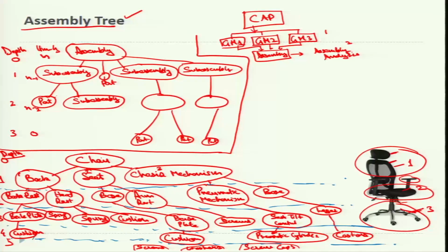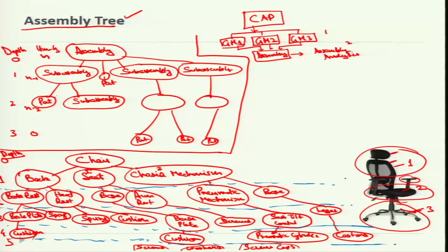So you can see, just like the decision support system or the decision tree that we use to take decisions, the assembly tree also has a similar pattern or hierarchy. How do we take decisions? While varying the geometric dimensions of any component. For example, the base plate size is previously decided as 15 inches or so. 15 inches is changed to 14.5 inches. Accordingly, where we fit the armrest and the back cushion, the dimensions would change. The decision will keep on changing. While changing a single dimension of a single component, or within a sub assembly, the overall assembly is affected or has to be changed.